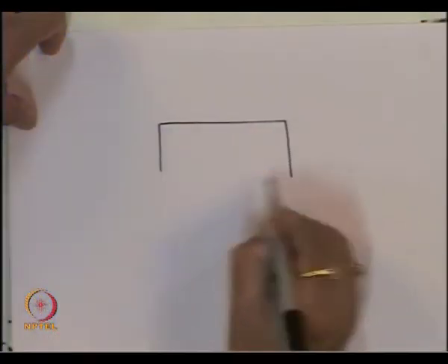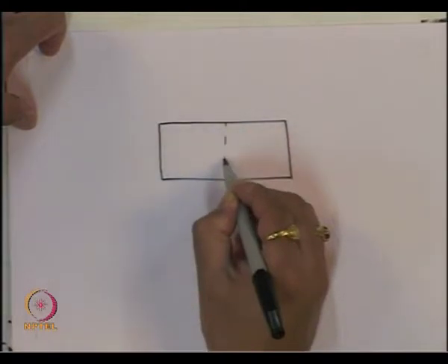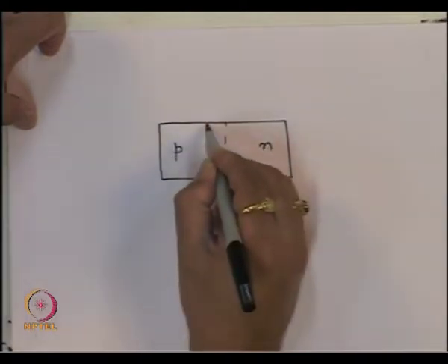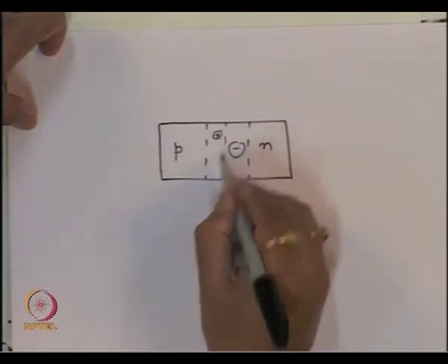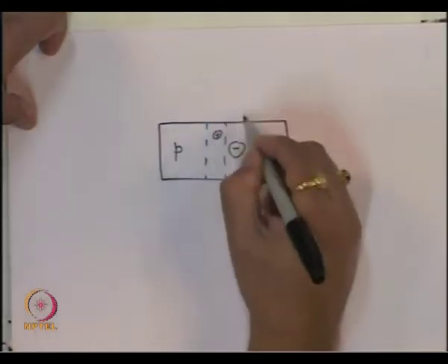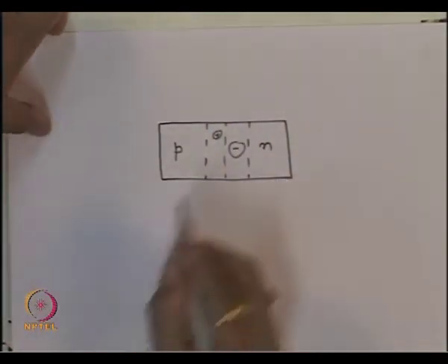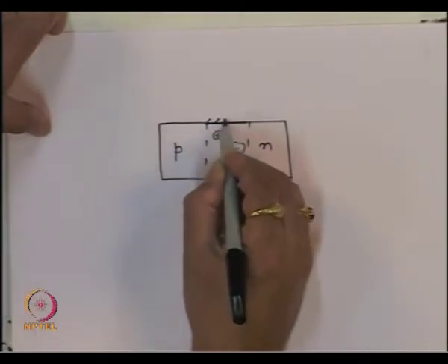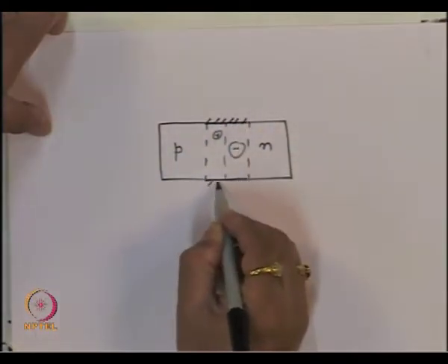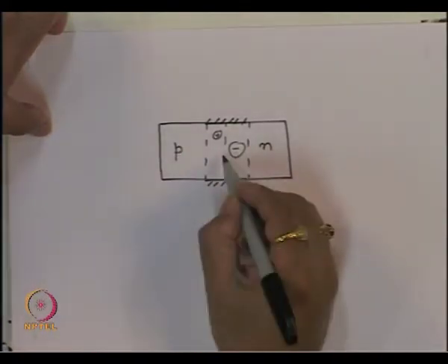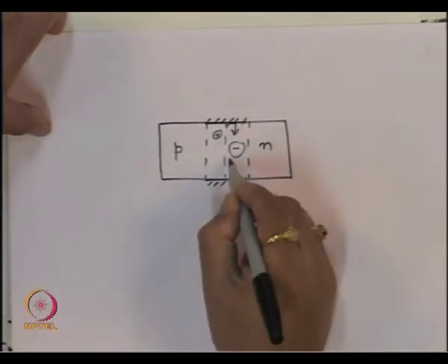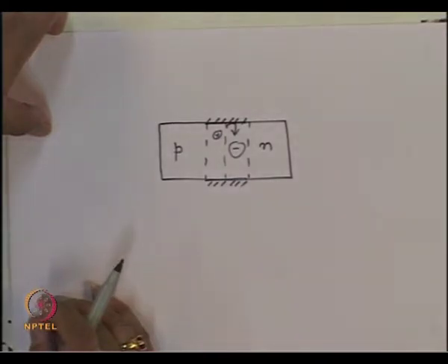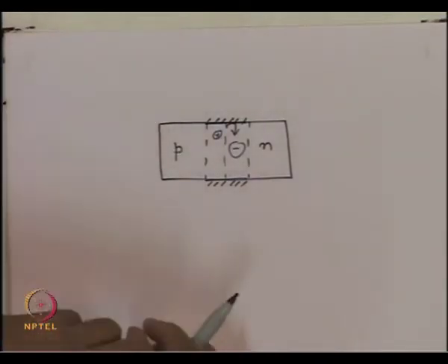So, in fact, schematically if you see, if we take a PN junction and you are having a depletion region here where the recombination of electrons and holes takes place, and the light, let us say, is trying to come out from this side or this side. If we create certain reflecting regions here, then the photons which are generated inside these regions would get reflected by this. So, the photons will be trapped inside this region and then we will have a stimulated amplification of light.